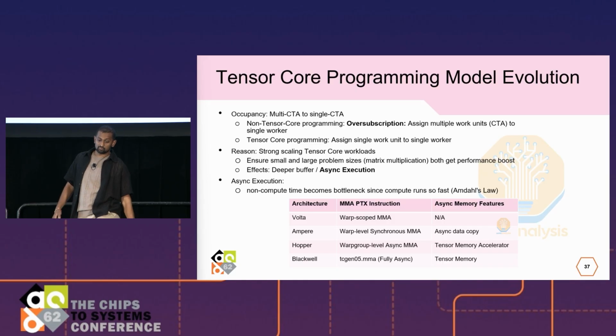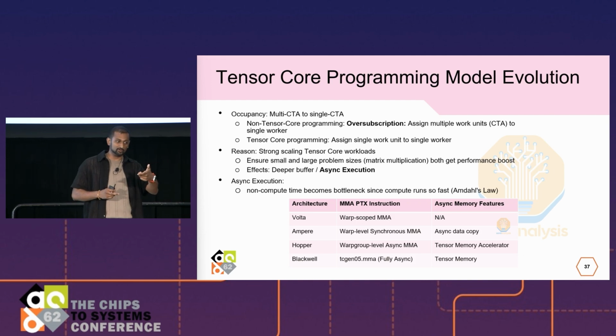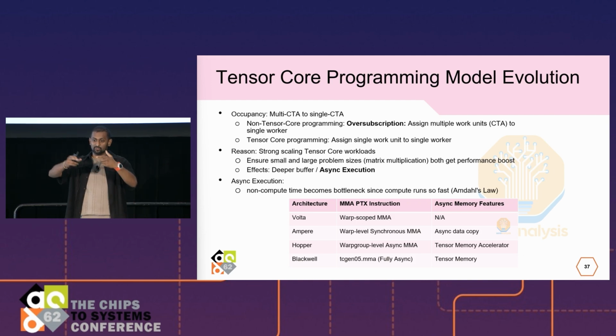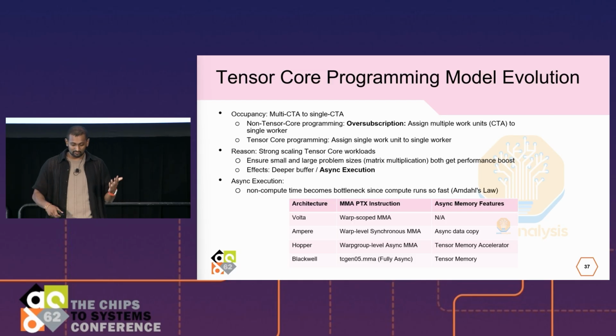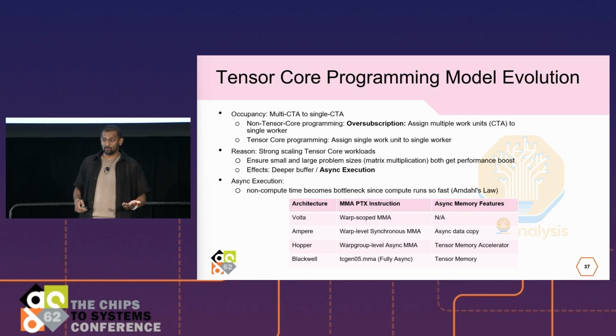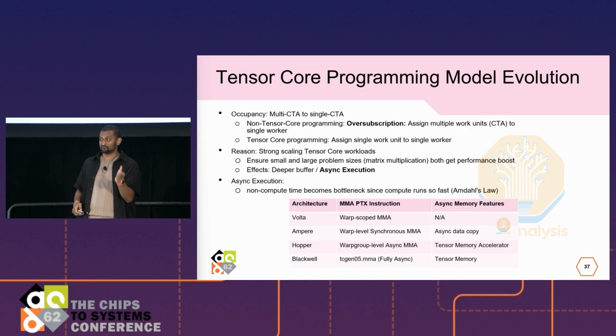The programming model especially has turned to what's called asynchronous execution, right? Instead of you load, you compute, you actually have different stages where you can load the memory, load a tensor or weights into a certain array, and compute separately, so you're always ping-ponging around. This is very difficult, and this is not the standard GPU programming model, which is parallel execution. It starts to become more like a data flow, right? And that's what NVIDIA has implemented on the latest Blackwell generation. There are actually 3 separate memories for each tensor core: there's memory within the tensor core, there's the reg file, there's the shared mem.